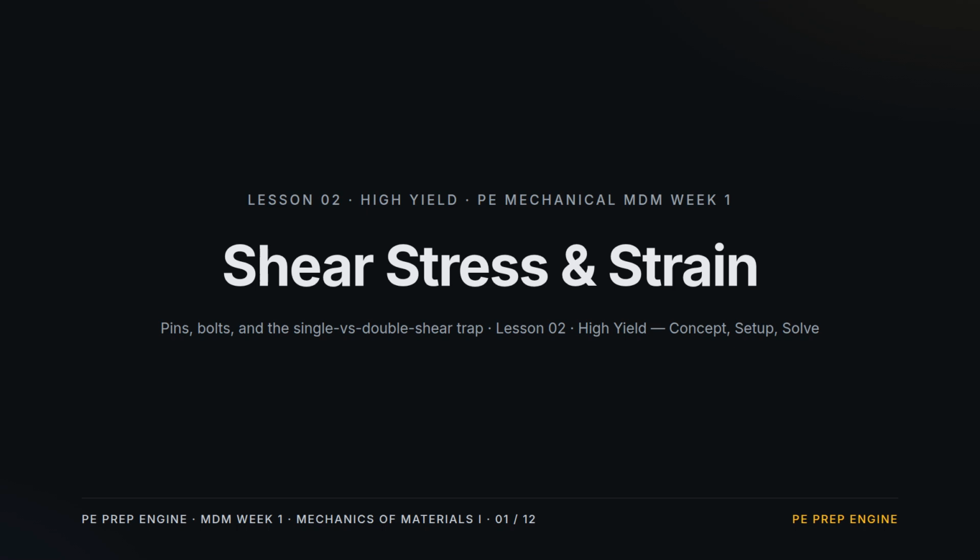Lesson 2. Shear stress and strain. Axial stress pulled the fibers apart. Shear slides them across each other. 3 one-line ideas. Shear stress is force over the area that resists it. Shear strain is stress over the shear modulus, and the shear modulus ties back to Young's modulus. Then the one distinction that trips people every exam: single versus double shear.